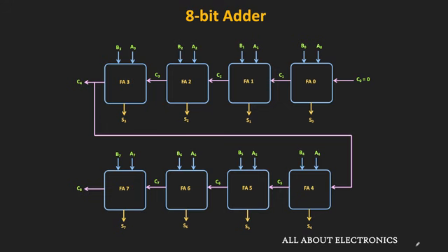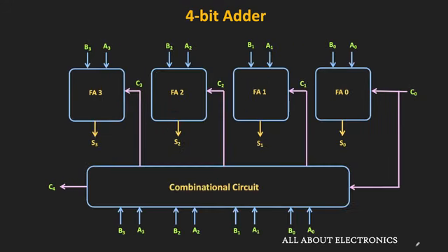Let's say we have a combinational circuit which can generate the carry bit for each adder from the input bits, and these carry bits, that is C1, C2, C3 and C4, are generated at the same time. If we can design such a combinational circuit, then each full adder does not need to wait for the carry bit from the previous stage. A similar sort of concept is used in this look ahead carry adder. Of course, the exact circuit of the adder is a bit different, but the design philosophy is very similar.